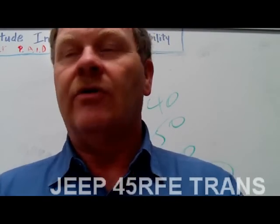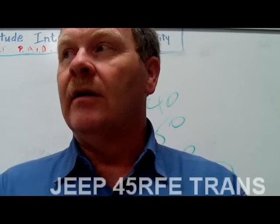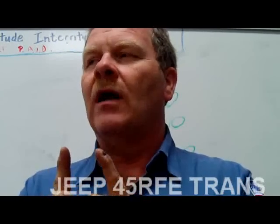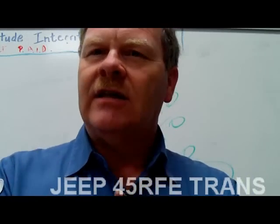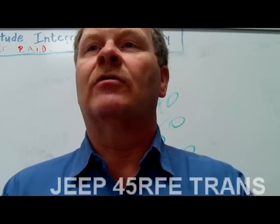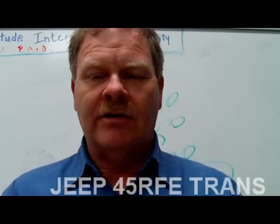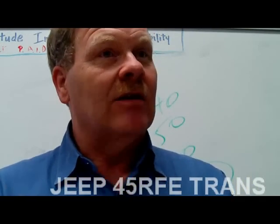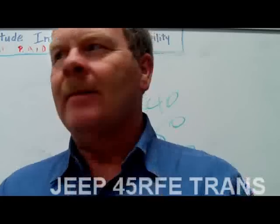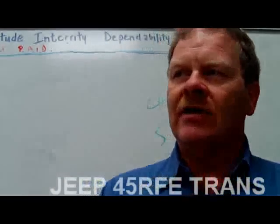Any module that won't talk, you want to see if it's powered and grounded. Real important. You also want to make sure, let's say it's powered and grounded, but it's working, but it won't talk, you want to see if the network wires that go from the module to the DLC under the dash are cut. I have seen people get under the dash when they're rooting around trying to find a wire to wire up a radio, snip, cut some of those wires. And now all of a sudden your scan tool won't talk to some of your modules. Now the module may still work, but you're trying to pull a code because you suspect something going on there. You got to be able to recognize. Look at the big picture, guys. Okay, we had power, we had ground, but we had no communication. We had no speedometer operation.